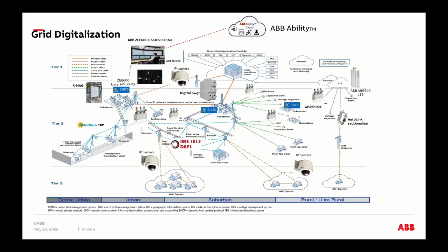When you're designing a system, if you have an existing upstream SCADA, for example, you need to make sure that protocol matches. Usually you're going to connect through maybe an OPC UA. So your system becomes a gateway to that system, right? Sometimes you're doing some logic in your HMI. It's not only an HMI, it's also a data concentrator. It could be an automation controller. It could be anything that you're doing with it. And I will go through those one by one.